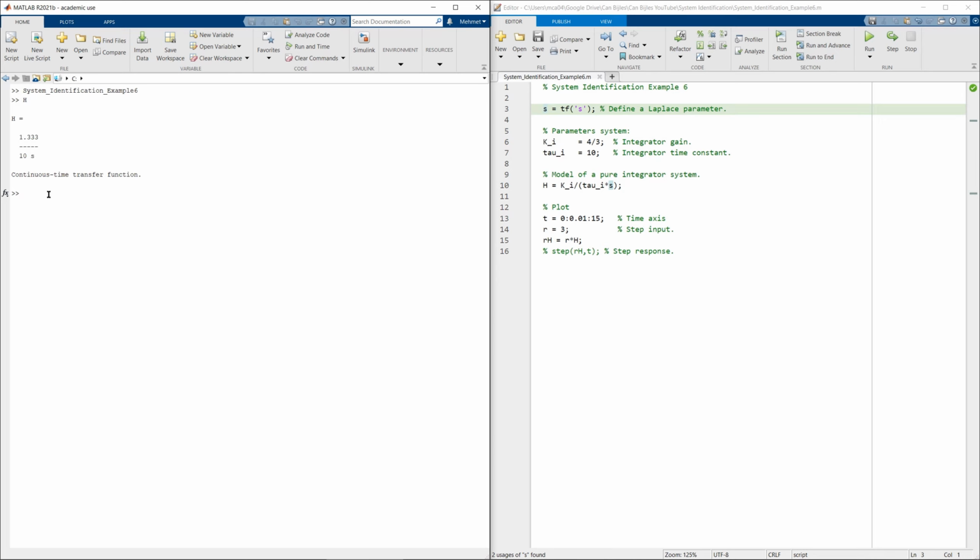Of course, you can have it also in a different form, which is the 0 pole gain format. Let's also do that. So 0 pole gain format. Then you will have this expression. You can see directly that this is the value, what is actually the 2 over 15. So this is actually approximately 2 over 15, and it is actually the same as this one. So it is actually what you prefer.